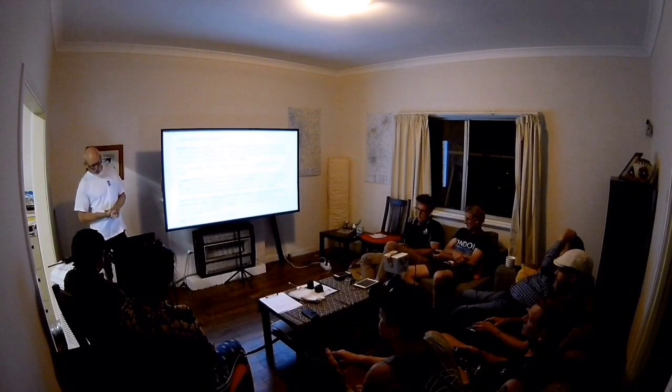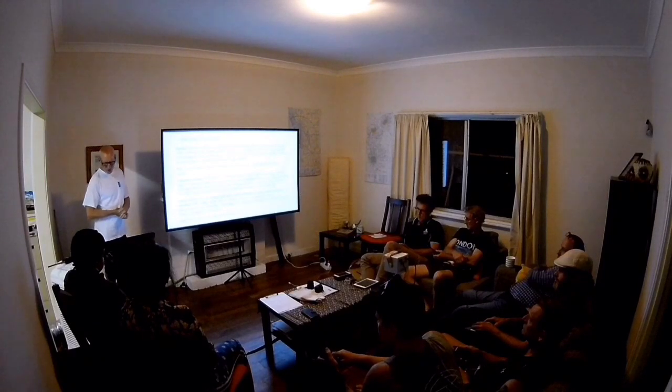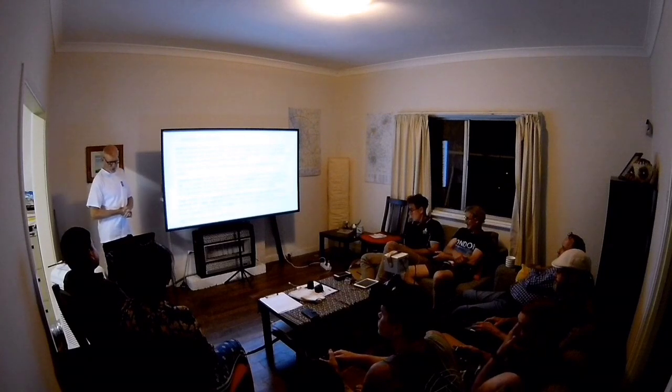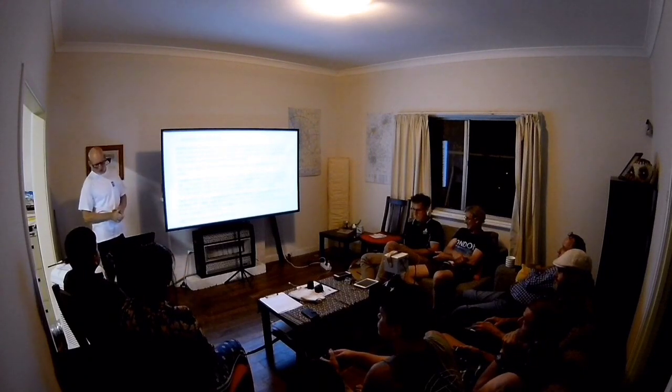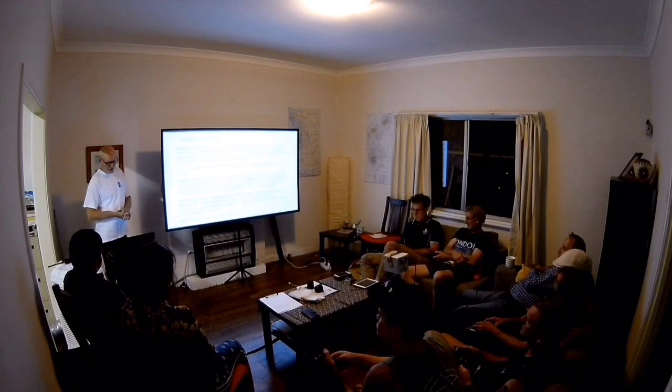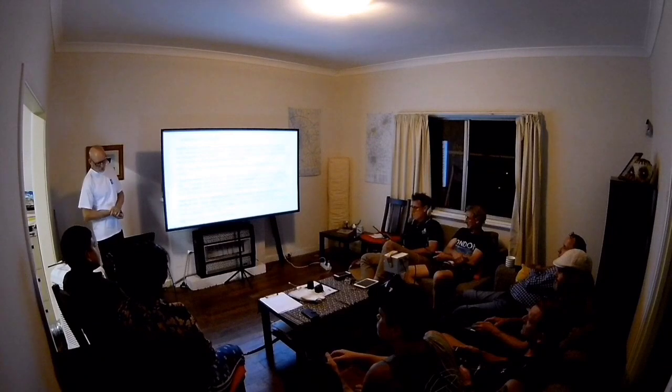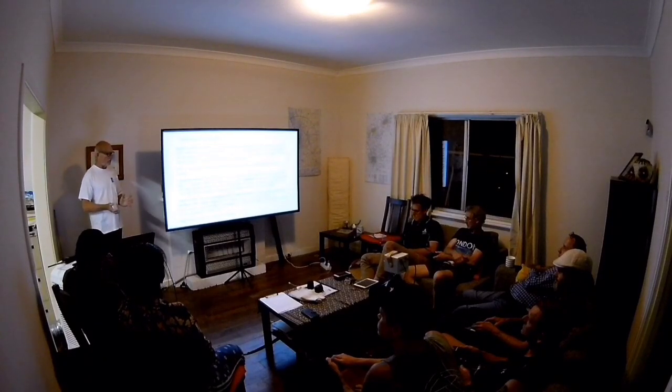Okay. To remove unwanted background noise, known as static or hash, switch on the squelch switch. If there is a squelch knob, turn it until the hash just disappears, until that static noise just disappears. Don't turn it too far or you may lose your incoming signal.